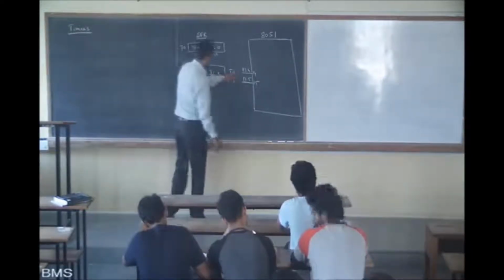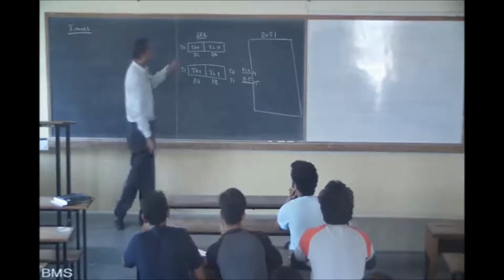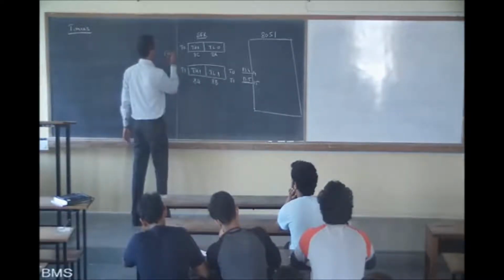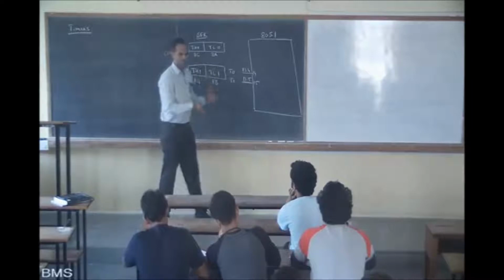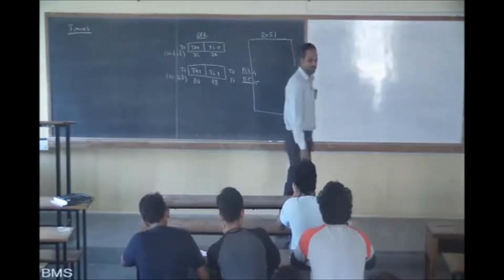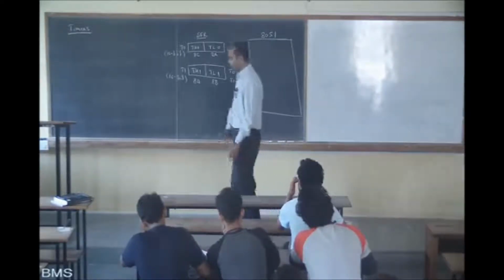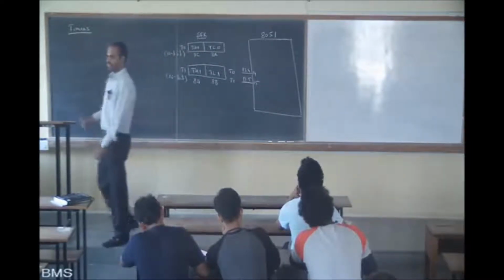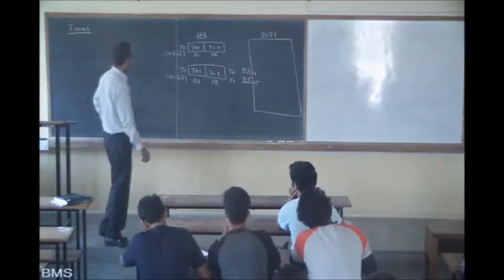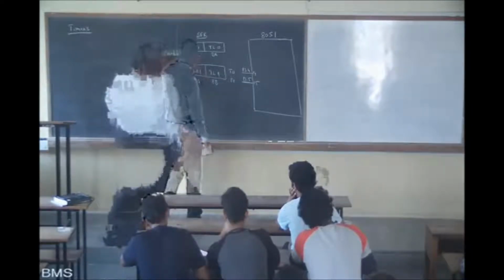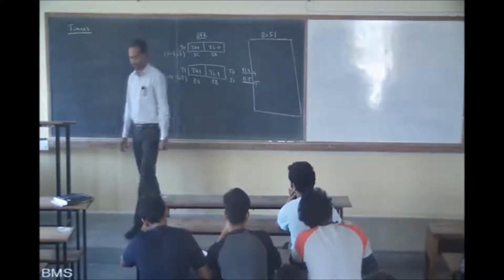These two pins will correlate with these four registers in SFR. We said T0 and T1 are 16-bit registers, because internally each is a combination of two 8-bit registers. Everything is an 8-bit register now, except PC, whose structure we don't know yet. Every other memory space in the 8051 is 8-bit only. Now we should see how we handle these two registers through these pins.